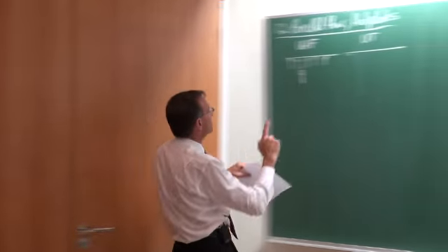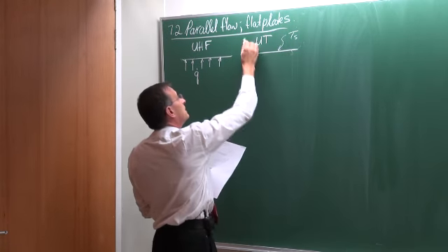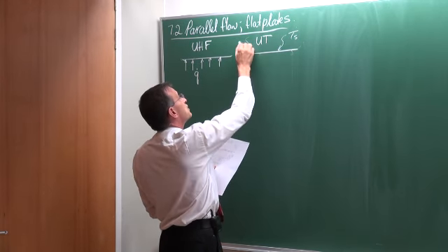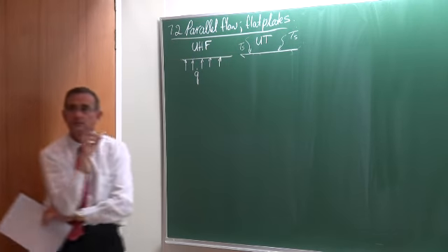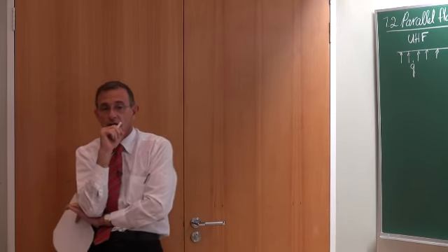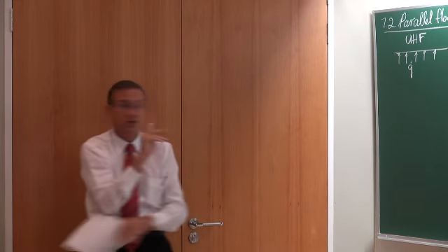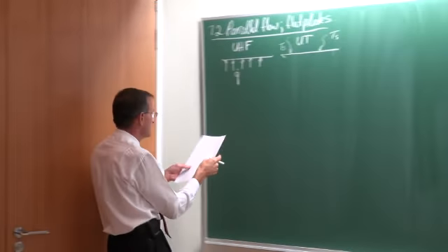In the other case, the application might be that the surface temperature remains constant. The result of that in terms of the Nusselt numbers is quite significant, so it's very important to distinguish between these two cases.